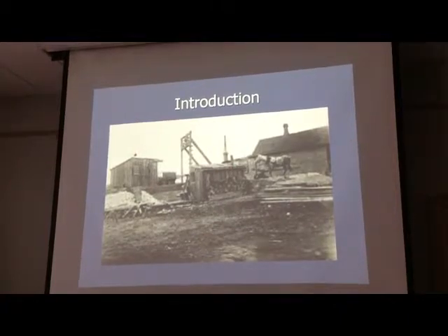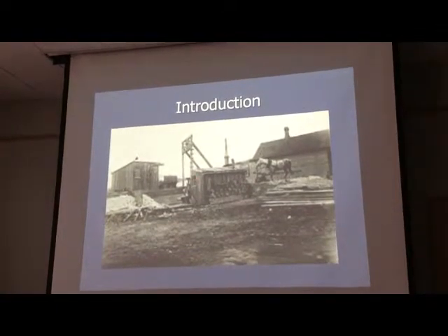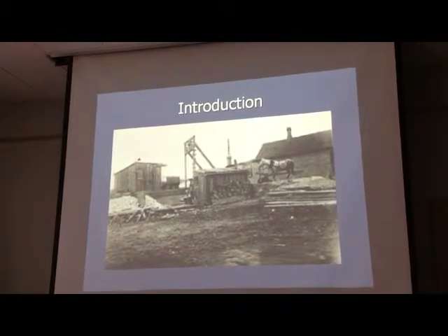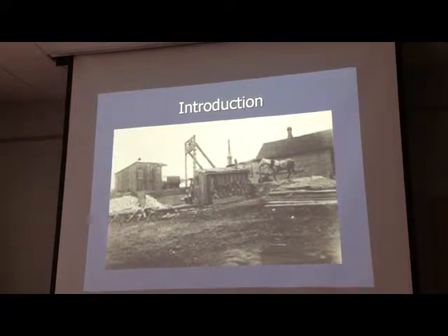This one here, you can see there's no guides. It's a simple two-post head frame. This would have been bucket hoisted, and that's an easy way. If you don't see any guides on the head frame, it's probably just hoisting with a bucket. And the problem with that is it'll twist, it'll bang against the sides, and if you're riding one, you can get hurt pretty easily.